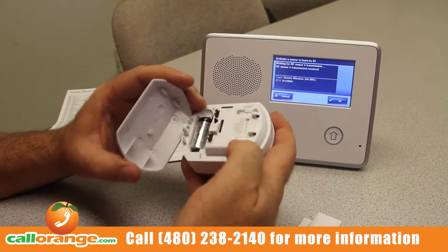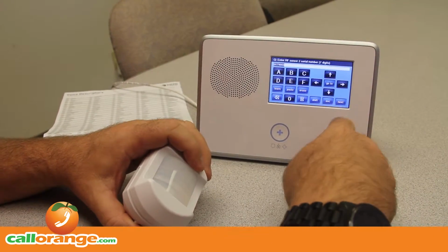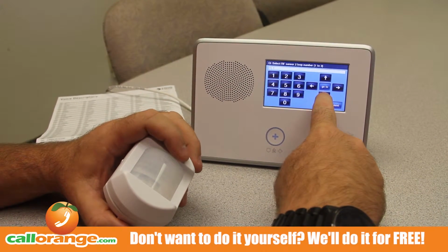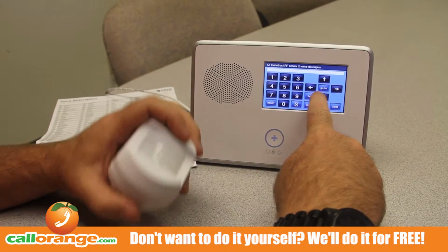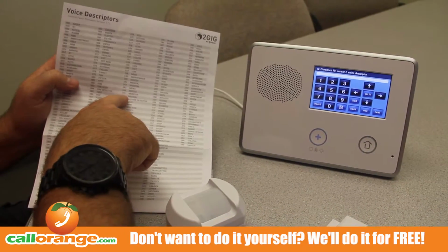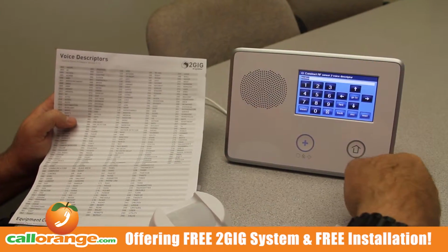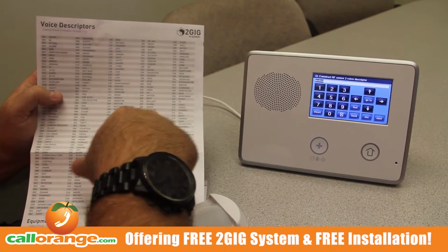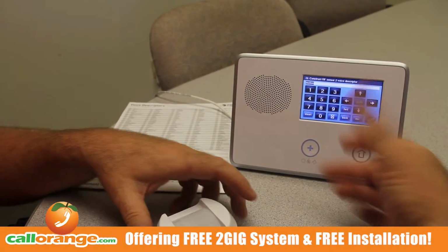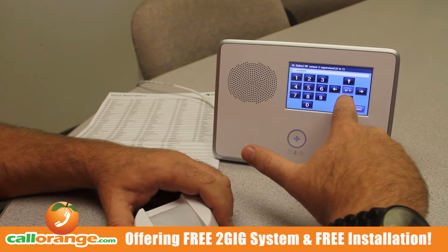Okay, we got 969, 969, there it is. Okay. Down arrow, it's new because it's in my equipment. It automatically defaults everything, enabled. It's asking for the description. Motion is 146. Insert 146, it tells you it's a motion. You could put, you know, bedroom motion, master bedroom. You could really distinguish and add what you want to do in there. For all intentional purposes, I'm just putting motion right now. Down arrow, defaults everything.